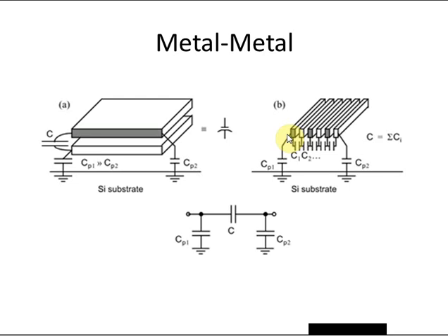So regardless of which approach you use, again, some pros is that these capacitors can be made symmetric. They provide a capacitance that's very linear. There's no depletion region that's changing as a function of voltage or anything like that involved here. So they're very linear capacitors. And you at least have some control over the parasitics in that you can decide what layers of metal to implement them on. So you can make them have low parasitics by using high metal layers, or you can make them have a very high capacitance density by stacking layers on top of each other. So these are, again, the most common types of capacitors used for critical analog signal path applications.